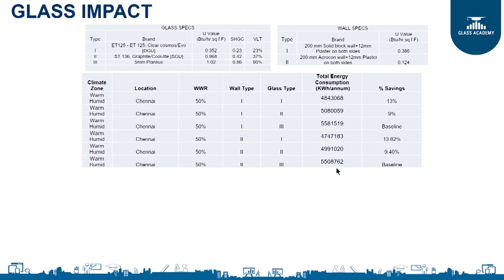So you can combine these simulations, which are energy simulations, with the daylight simulation, and match the two and see how you can actually improve your daylight and at the same time use a lower SHGC. That involves a lot of studies on sun path and trying to align your building to the right kind of orientations, so that you get the optimal light inside the building, right? All these studies can give you a fair bit of insight on what type of material to choose from when you do your energy studies.